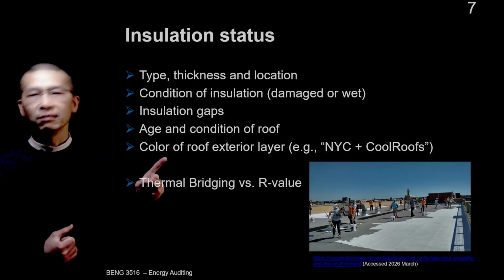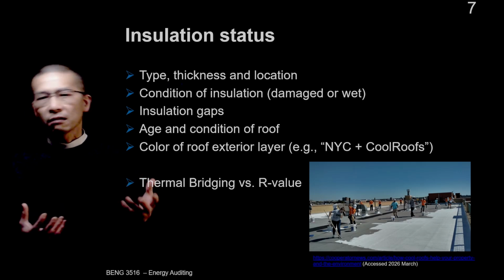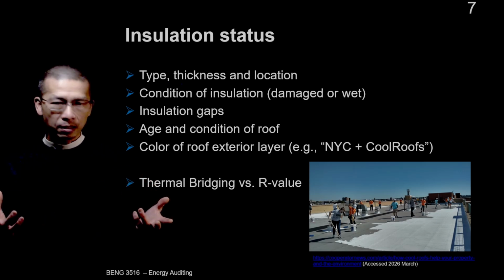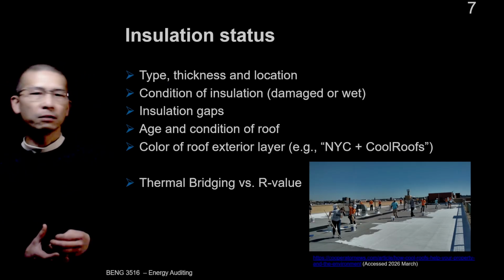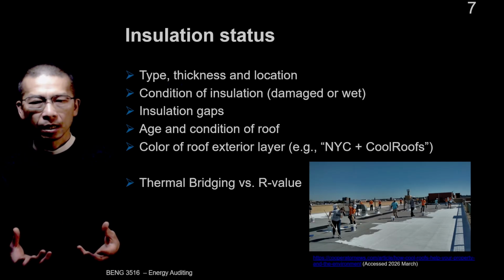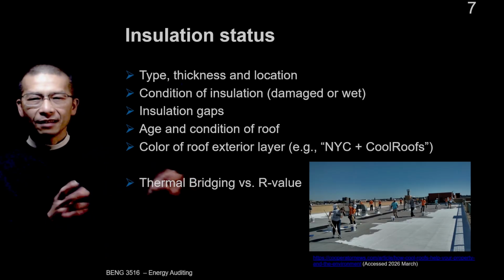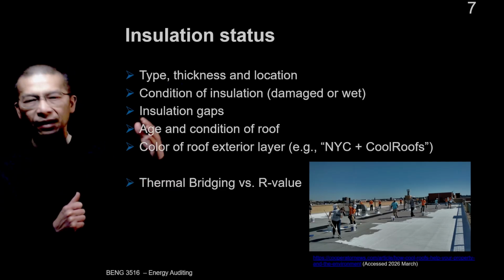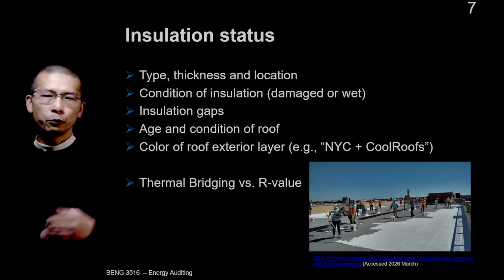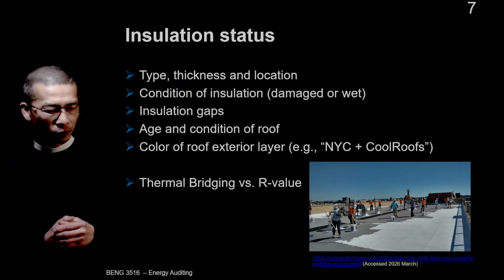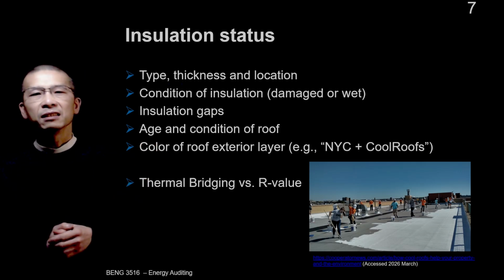Okay. Now, color of the roof. In our climate here, a dark color roof can help with the solar gain in the winter time, but in most commercial buildings, the cooling penalty in the summer is much higher. So use a light color cool roof, right? It has higher reflectivity and can significantly reduce the building's cooling load by reflecting the solar radiation before it ever gets absorbed and enters the insulation layer.